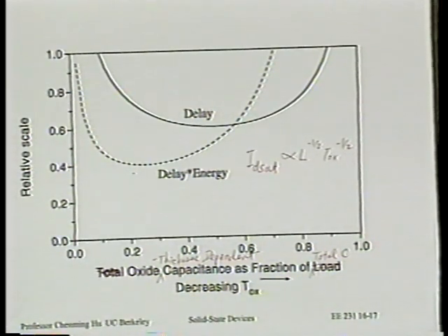You get only one oxide thickness to drive all kinds of gates. So you can think, in the future, when we want to try even harder to get the performance up and the power down, maybe we could even introduce more than one oxide thickness. We already decided that we can tolerate more than one threshold voltage, remember? Why can we not tolerate more than one oxide thickness?